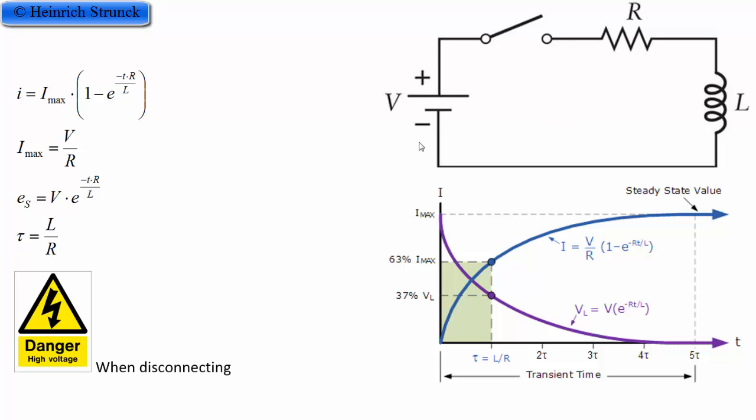And it, for example, can start generating the supply voltage, but it doesn't help bring a current in the system because the switch is disconnected. So the coil says, okay, I must generate an even higher voltage to bring a current, so that will keep the same current as before, and then the magnetic field. And the voltage will increase, and it can be many times the supply voltage.